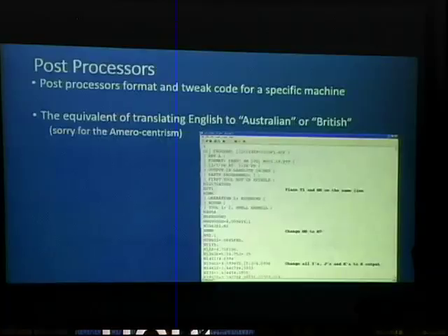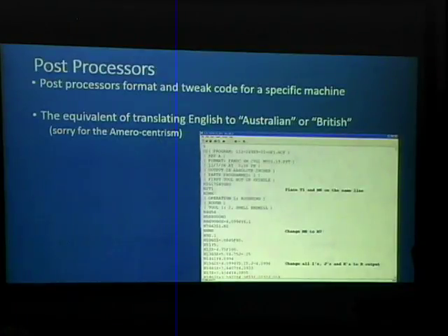So once we have it done in the CAM program, there is one more step. I mentioned that generally it's a standardized way of coding. At the end of the CAM step, before we get to the CNC, we go through what's called a post-processor. And the post-processor is this unique invention because despite the language being standardized, nobody implements it the same way. Different CNC tools want different things to be done in different orders. They want instructions to be given in very specific ways.